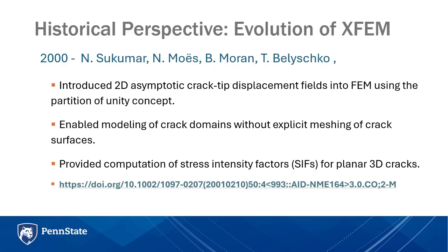In 2000, it introduced 2D asymptotic crack tip displacement fields into FEM using the partition of unity concept. It enabled modeling of crack domains without explicit meshing of crack surfaces. It provides computation of stress intensity factor for planar 3D cracks.